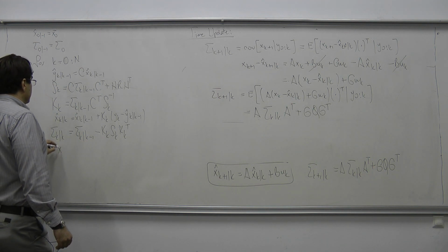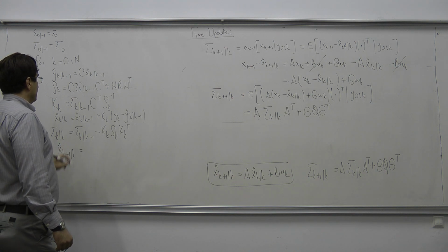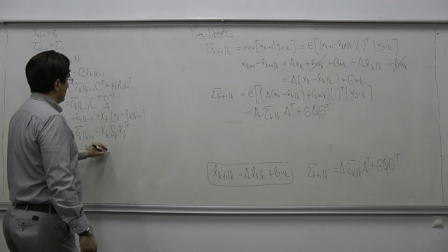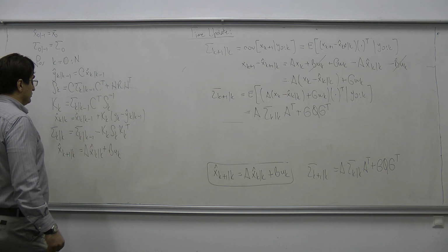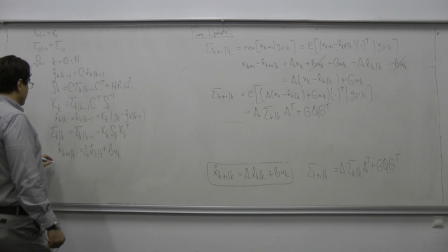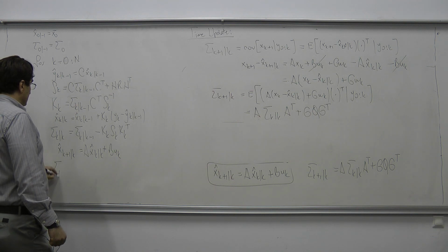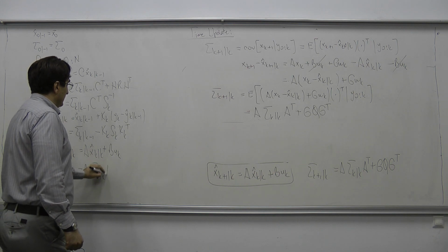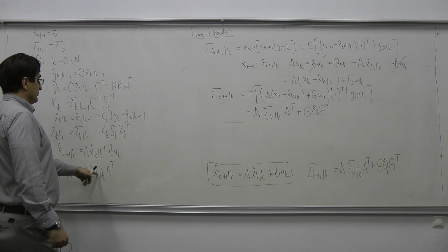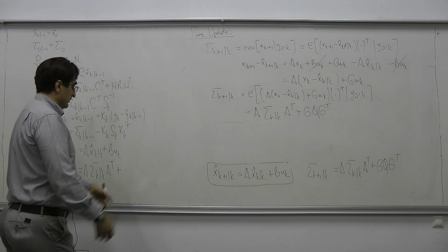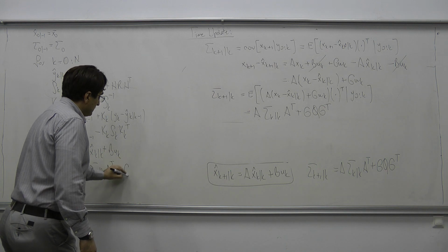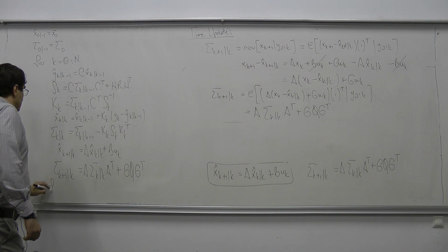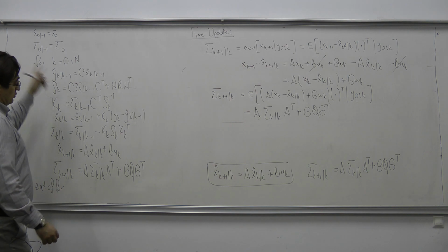And then the next thing is to predict the next state. x hat k plus 1 given k is going to be equal to A times x hat k given k, plus B u_k. The input enters into the picture, and then we predict the uncertainty of the next state. Sigma k plus 1 given k is A times sigma k given k, A transpose, the transformed uncertainty in x_k, plus the uncertainty of the process noise, G Q G transpose. Okay, so I can write here end of 4. And that completes our algorithm.